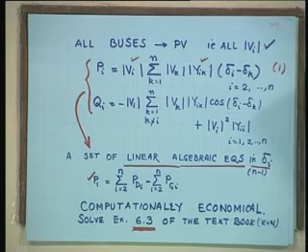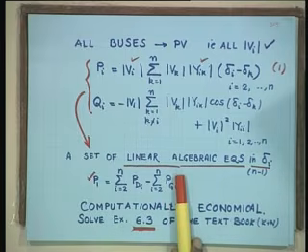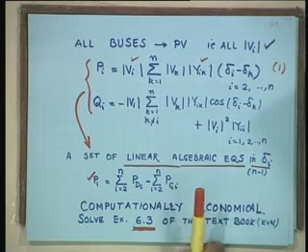Please solve example 6.3 of the textbook, which talks about this approximate method. Then you will realize how easy or how convenient it is to solve an approximate load flow. Obviously, the answers will be approximate using this load flow method, but those answers are indicative of things to come, because in 3 years there is no guarantee what you are assuming today will stay as it is. There will be some changes. So, there is no point in solving SLFE exactly for something in future which is really not well defined.